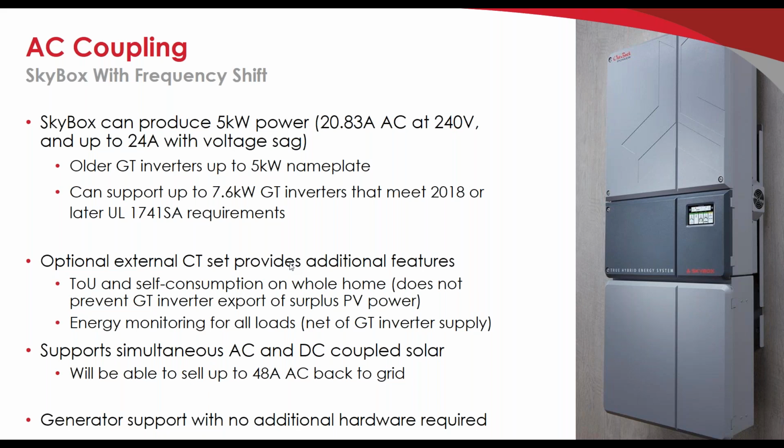John asks, how does your SkyBox know when the lithium is fully charged? Because the lithium battery has relatively constant voltage output until the battery is at low SOC. And John, the answer to that is that you can configure SkyBox to support a variety of lithium-ion batteries. We have pull-down options right now to support Simplify and Blue Ion preset configurations, for example. And when you do those, we do an SOC calculation. So we're not looking at just battery voltage.